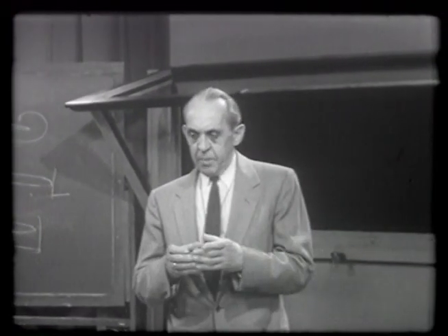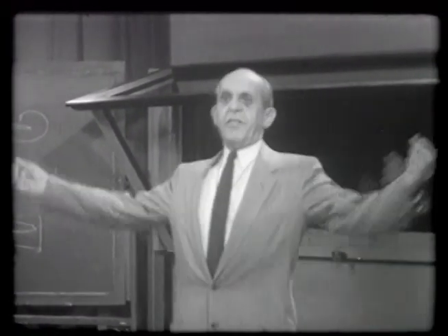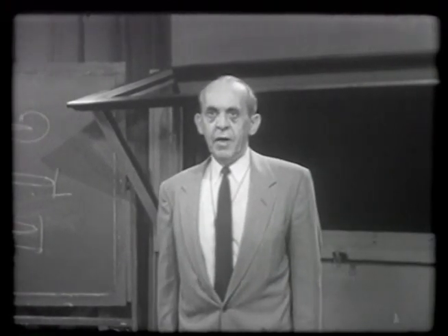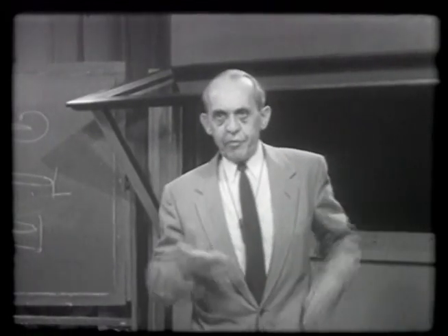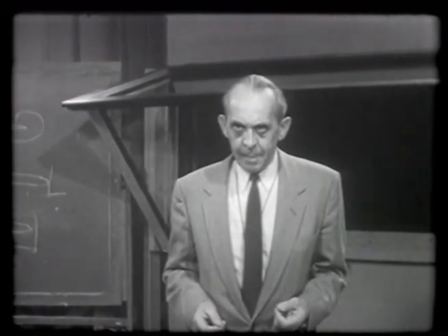You couldn't build a very slender wing because, well, you must think that when you fly, you have to suspend the weight. And when you build a very slender wing, then you have to have a very heavy structure within the wing to keep it from bending too much. And therefore, there is a certain technical limit in having wings with high aspect ratio.